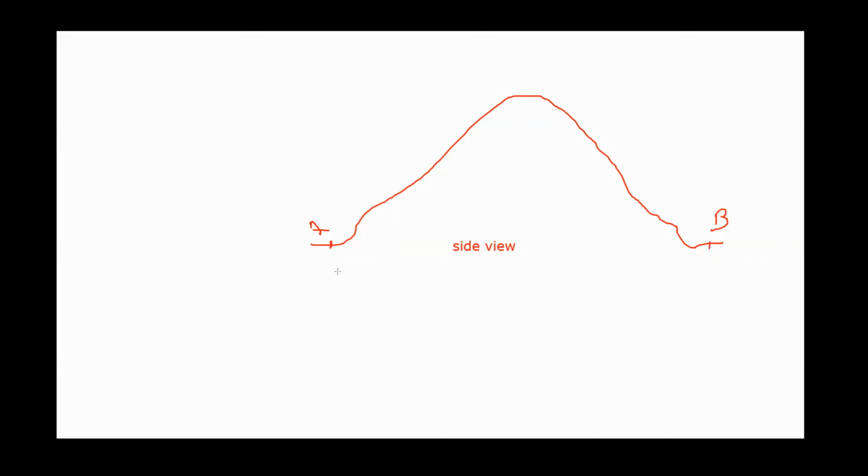And then you have a plumb bob here. Now the plumb bob for sure will not coincide exactly with the point. It can come a little bit in or out. No way you can get it exactly on the point. So you can't really say if the error or the line is going to be positive or negative. You can't say if you need to add or subtract. So that can cause you an error that's plus or minus, depending on whether you are in or out of the line here. Same thing here. You don't really know if your line is going to be in or out.